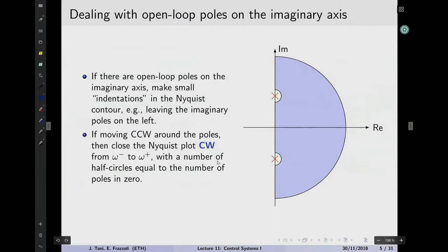So this is just a wrap-up of the previous class. We saw how to plot Nyquist diagrams. We saw how to do those with the help of Bode plots. We have never treated the case in which there are poles on the imaginary axis. The idea behind it is that we cannot draw the D region anymore as we talked about. We have to make some little kinks, we have to turn around the poles.